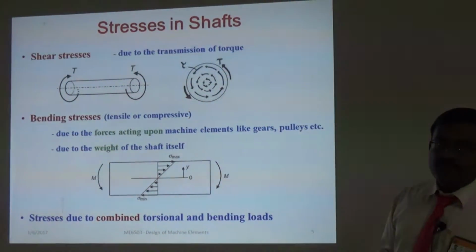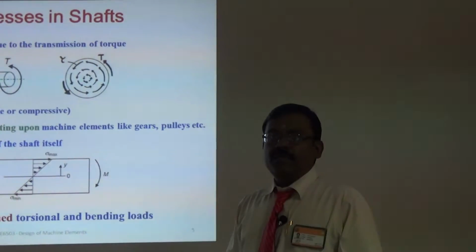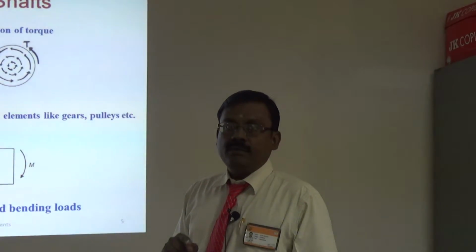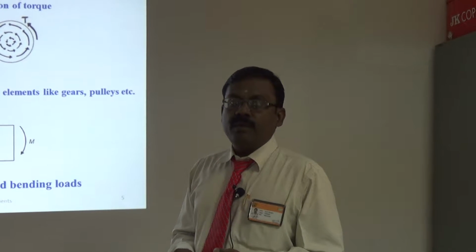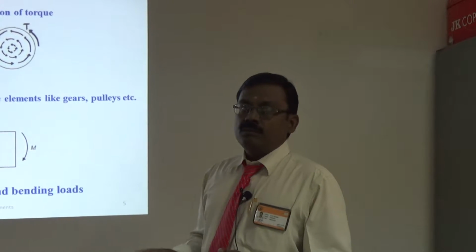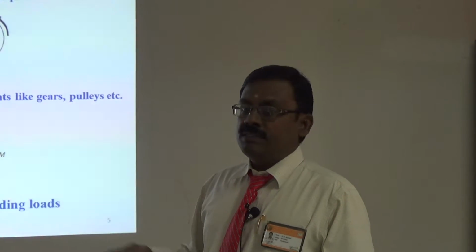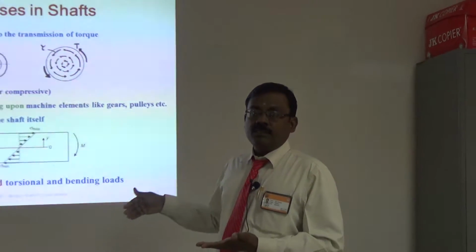So, to design a shaft, first we should know what are the loads acting over the shaft, whether it is subjected to purely twisting moment, purely bending moment, or a combination of these two. So, now we will go to the procedure of how to design the shaft which is subjected to different kinds of loads.